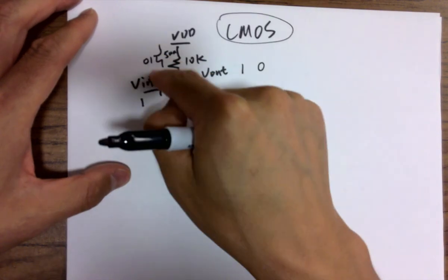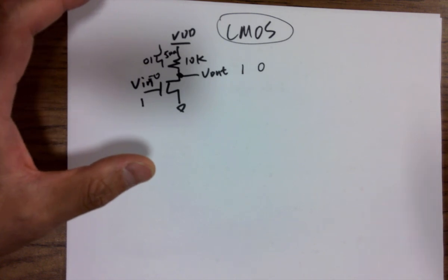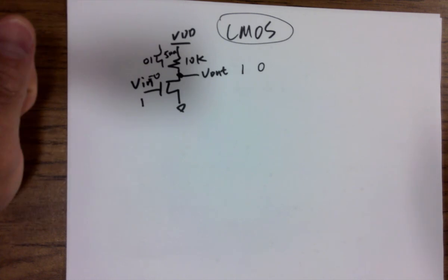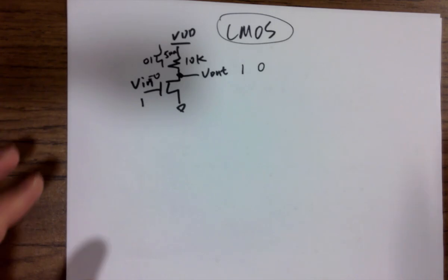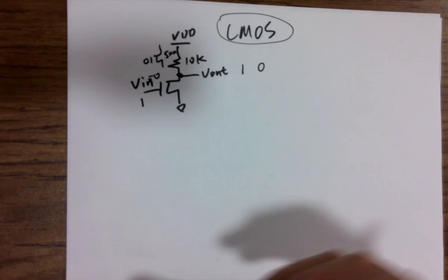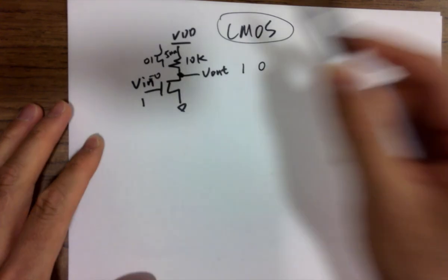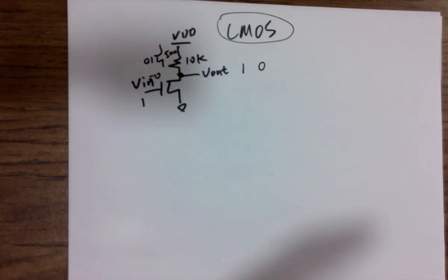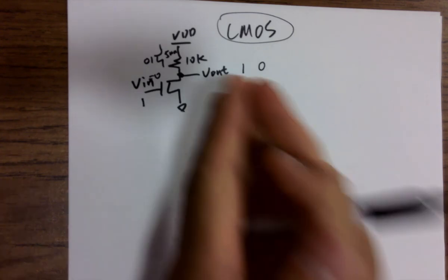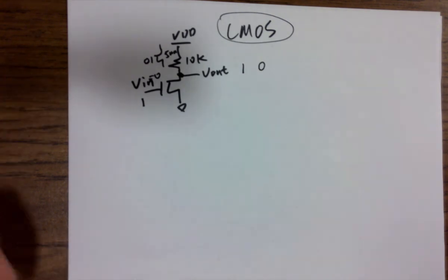So this is actually an inverter, and you can form all different kinds of logic gates by using PMOS and NMOSes. So it's the modern structure of the circuits, even for the 5, even 2 nanometer technologies, it's still not changing. It was invented, I don't know, 30, 40 years ago, but now it's still being used for the latest node from TSMC, even 2 nanometers. It's just the transistor structure and the number of metal layers that are being changed. And the smallest channel length is being changed, but all the rest are still the same. The logic gates are still logic gates. So whatever you learn here from the textbook is actually being used in the industry, in your modern devices.